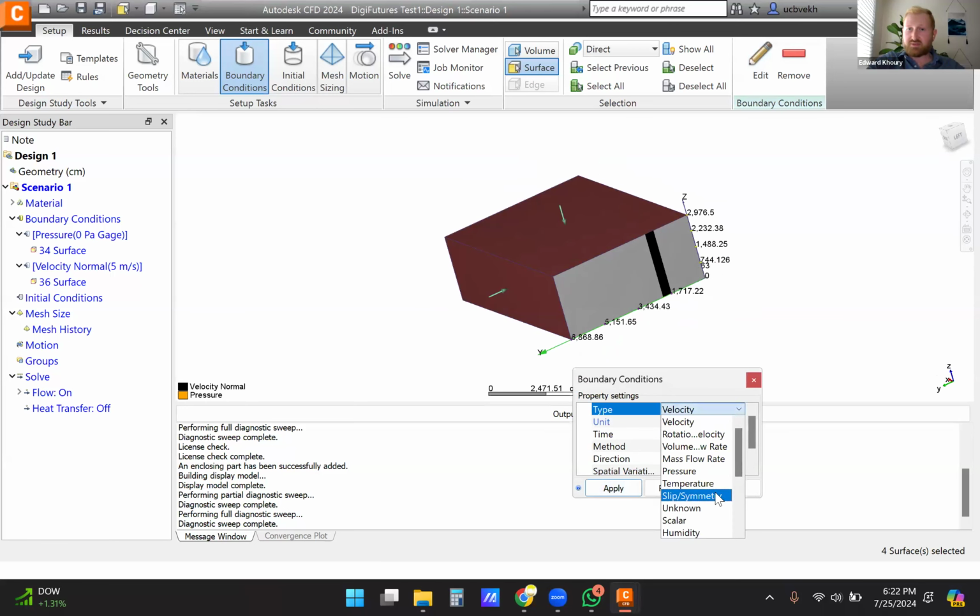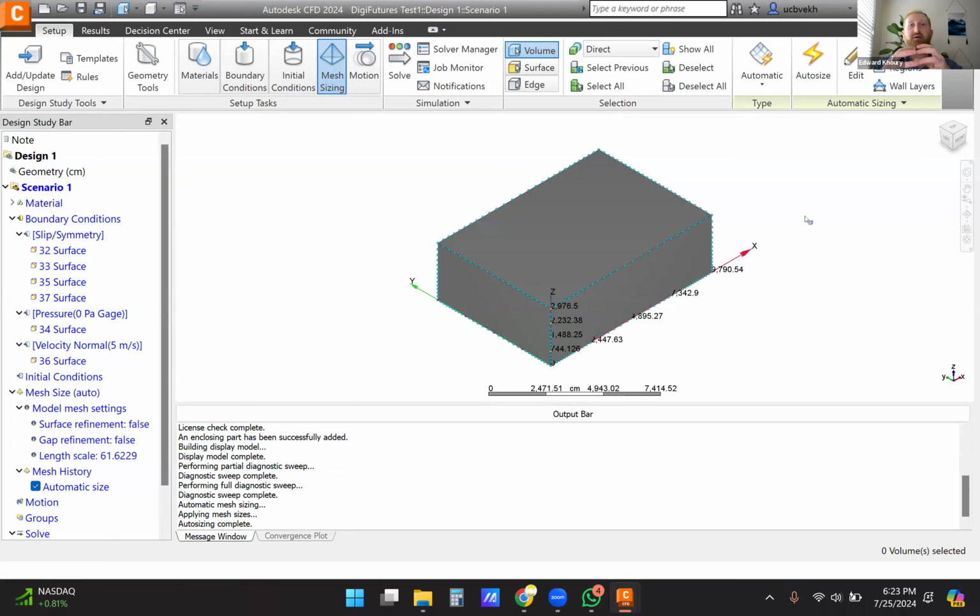Mesh sizing, which is what this is, needs to read and analyze the object in clusters, because if it does it all as one, it becomes too complex. So if you auto size, it'll automatically make connections of clusters and be able to read data individually amongst the entire model and calculate it. So now it's essentially set up. So you're prepared to do a wind flow simulation, or water flow in this case.